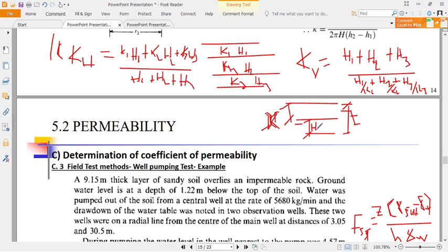Now, if you want to determine X, you already have the thickness H, and we assume that the properties of this material are the same as the properties of this other material. So you want to determine X: how much should you add so that you prevent uplifting or piping? Depending on how much water pressure head is going to come in, you are going to assume a factor of safety against piping equal to 3.